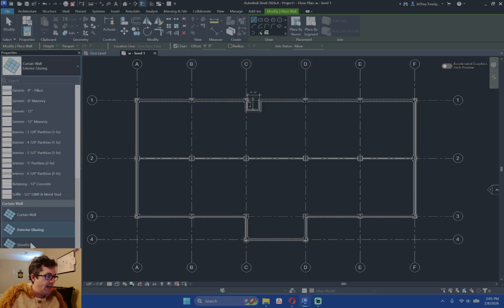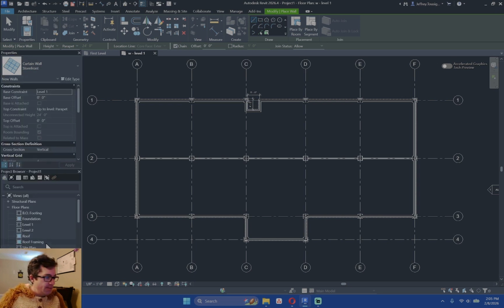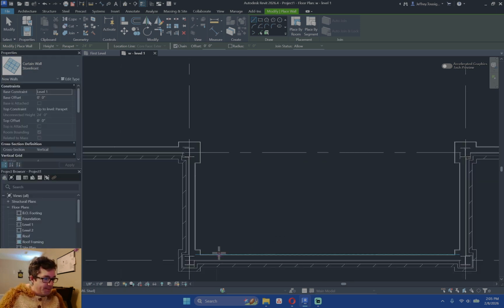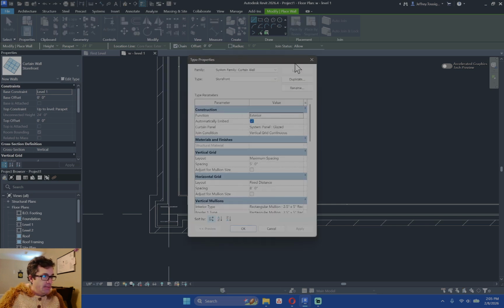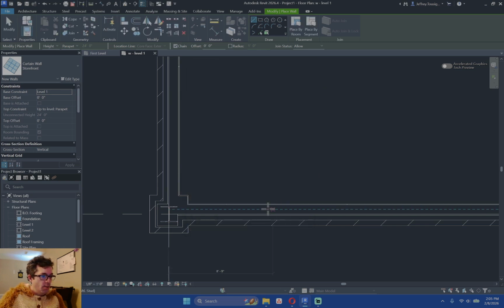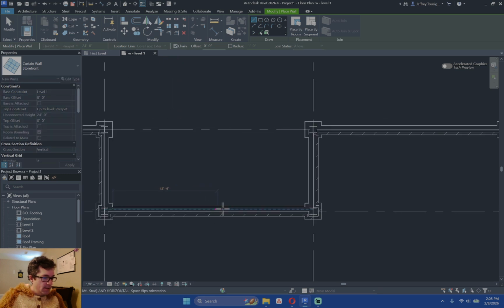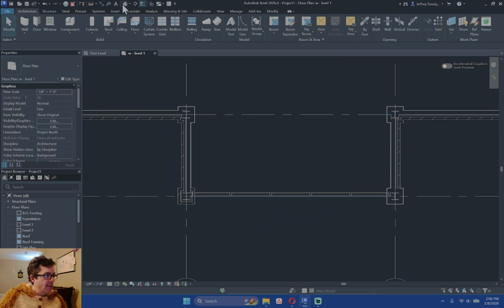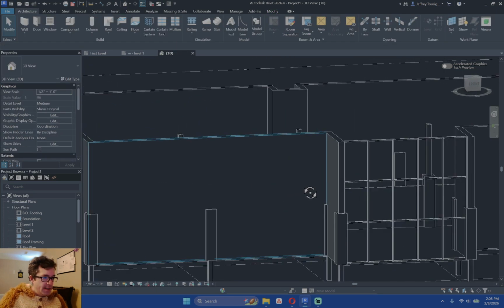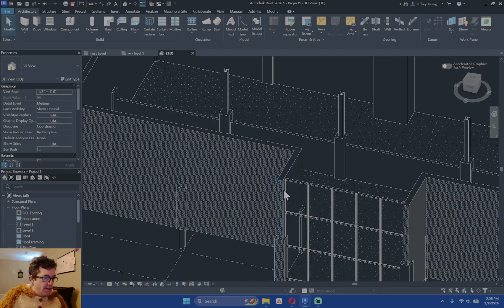I want to just have it propose storefront based on calculations of width and height and place mullions for us. And then as we further develop it, it will still be easy to customize. So I'm going to verify that this will in fact embed it inside of our model walls. And then I'm going to draw it from this column to this column. Now make it nice and neat, cutting it right at the columns, making that entire southern facade open,